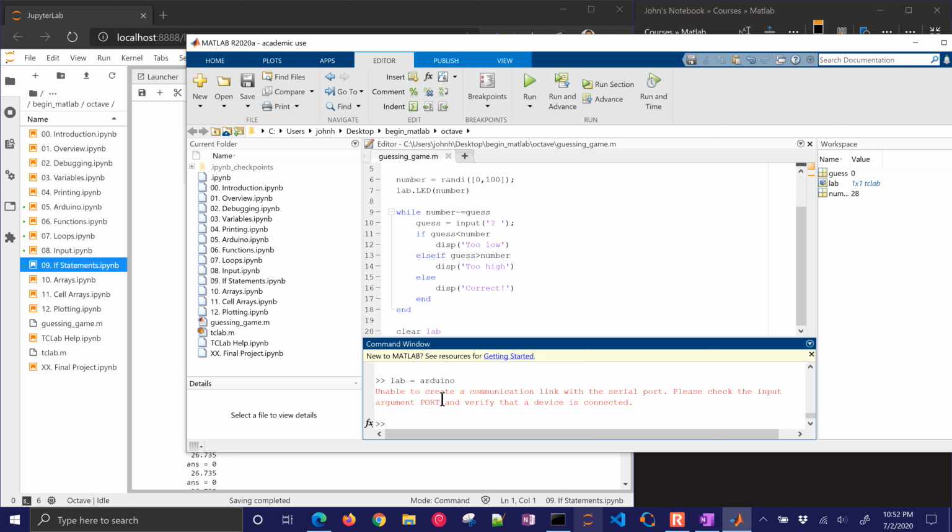All right, I'm going to just unplug and replug it in because it says Leonardo detected, and then I'm going to do Arduino just to be able to load the drivers for Matlab. So I was using Octave before. Matlab will go in and just load the drivers so I can use it in Matlab instead.